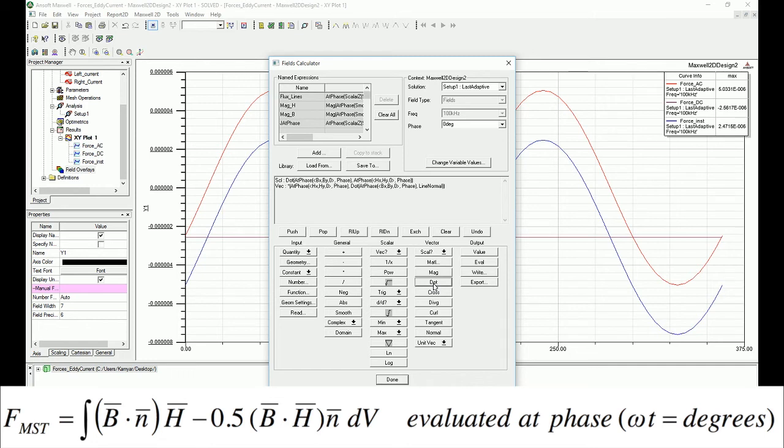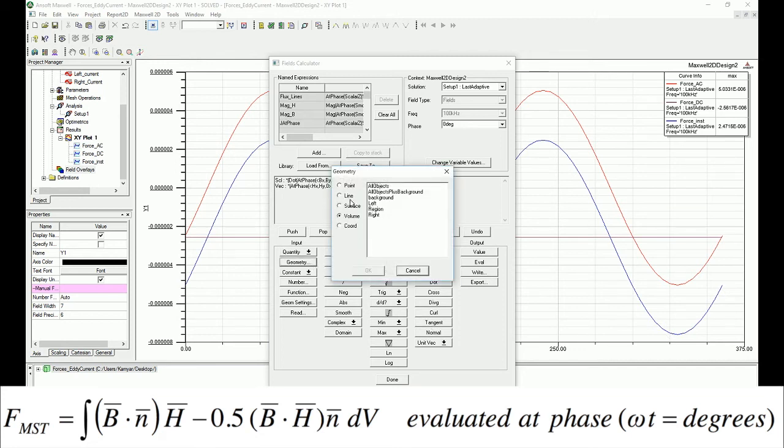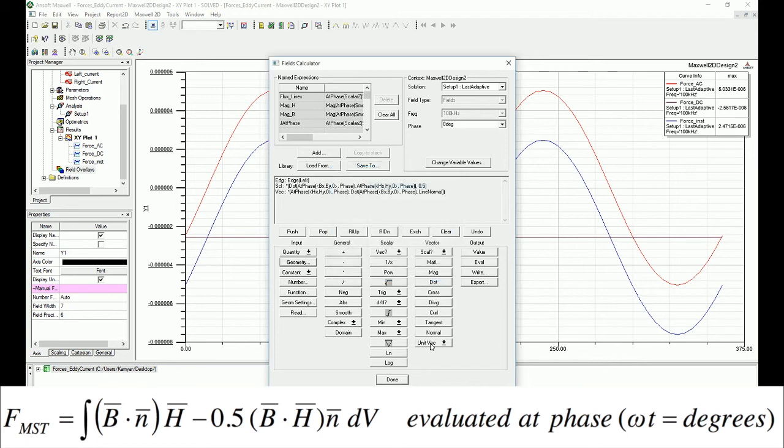Now we want to have the number. I know that this is getting pretty annoying, but it's a big formula, you basically have to deal with it. So I'm having times 0.5, and then we will multiply by that, and finally we go to the geometry and select a line, and we are trying to find the normal of the line for the left. So we say left, and then on the unit vector we select normal.